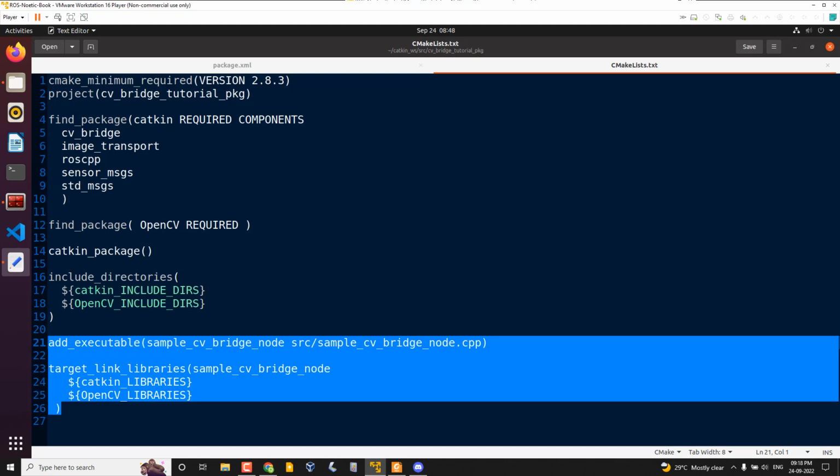These kinds of things come up only when we are out of RAM. Memory is the biggest constraint. CPU is also a constraint, but if you are using the Jetson series and doing deep learning, a lot of processing can be diverted to the GPU. But CPU is again a bottleneck.